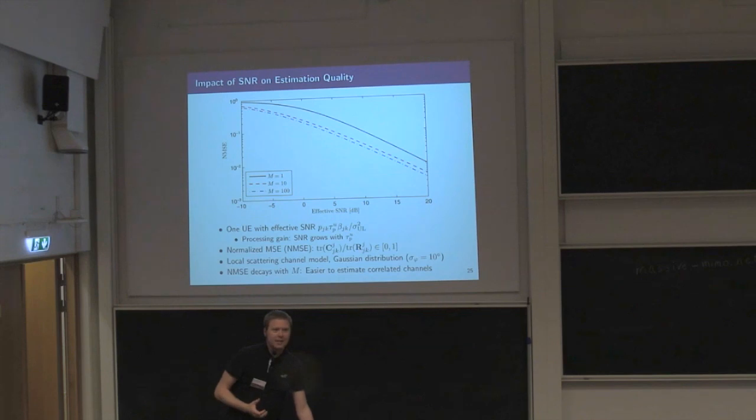It's like you have, say, 100 antennas, but the thing you're trying to estimate is actually only 20-dimensional or 40-dimensional, because that is how many large eigenvalues you have. And that will mean that there's only 20 or 40 antennas that contribute to channel hardening, so you have a less hardening effect, but you have a better estimation quality because you only have to estimate something of smaller dimension, approximately.